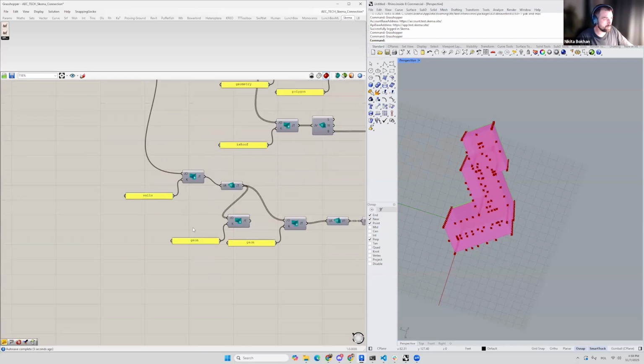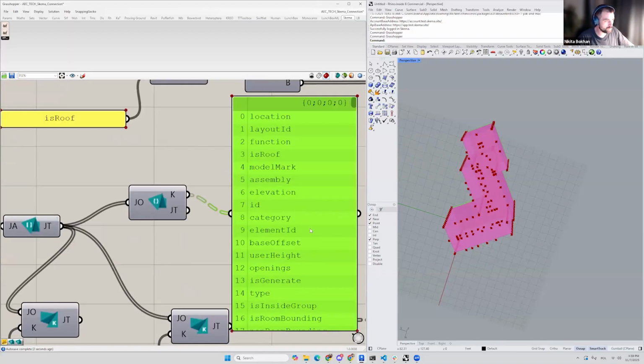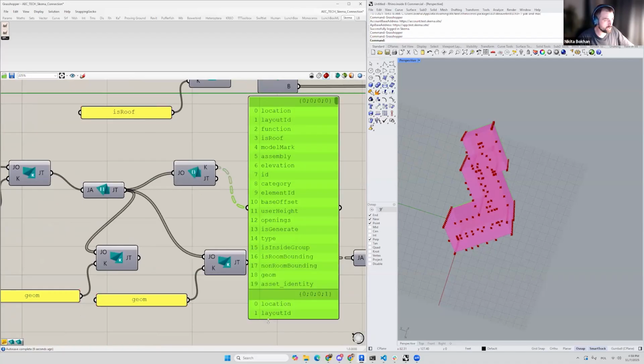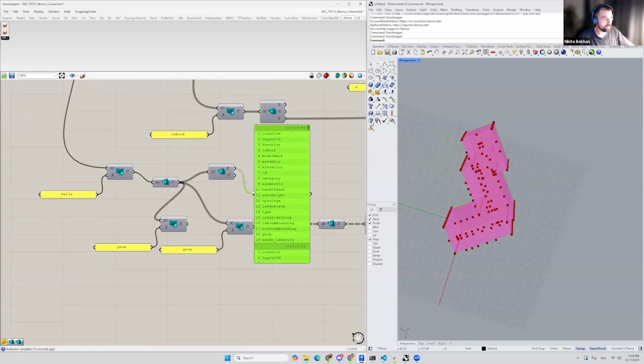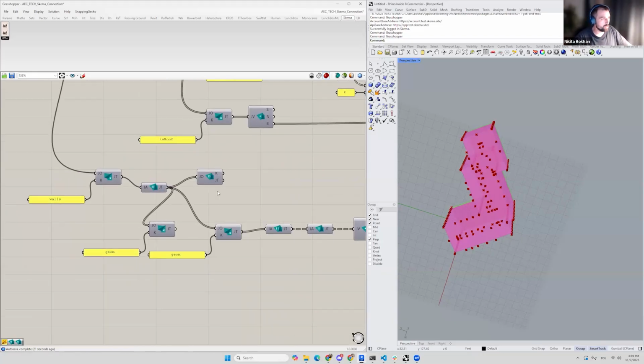Here I read all my keys. So as you can see, our walls have a property elevation, which gives us the elevation of each wall, because this is how it's easier to reconstruct in Revit. We need to know start Z and elevation in this case.